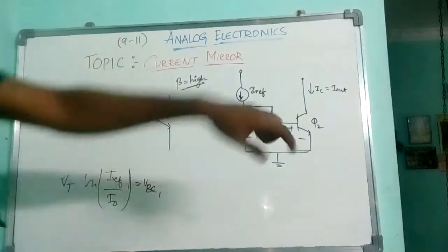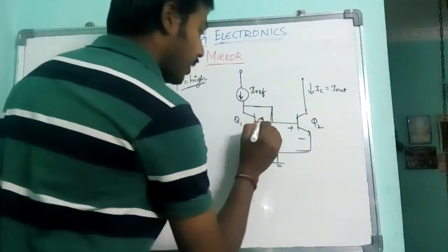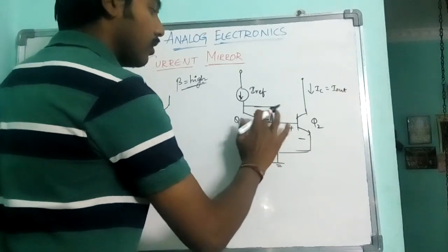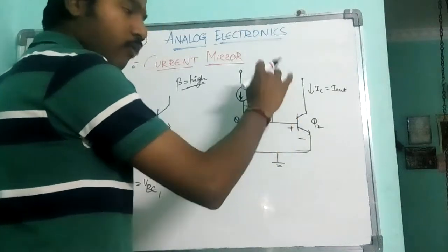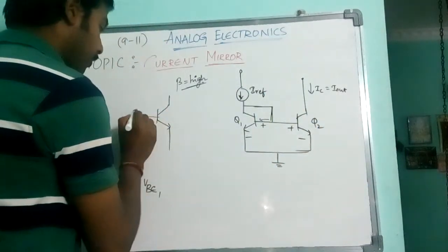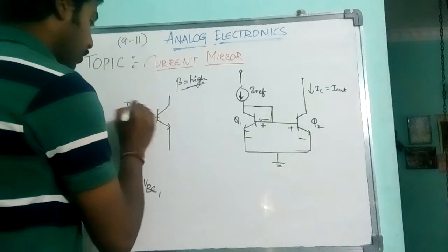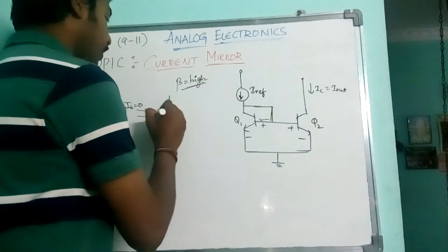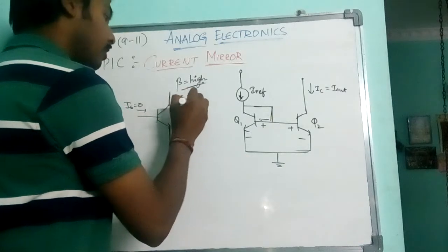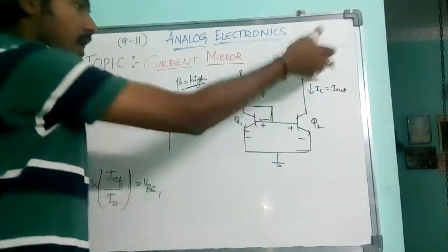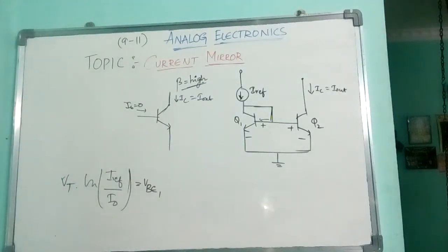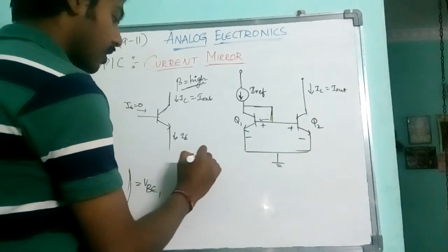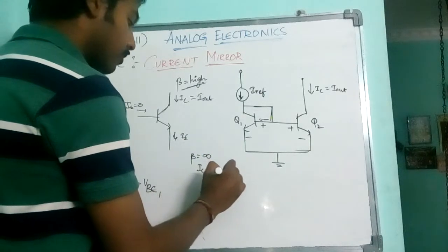This is the general circuit. That's it. What is available there? So here the current is 0 in the previous circuit. No current is flowing here, so even here there will be no current. IB equal to 0, so beta is a high value. Whatever it might be, this is IC here. This is the same as I out. IC same as I out. Whenever beta is high, IC equal to IE, that is equal to I out here.